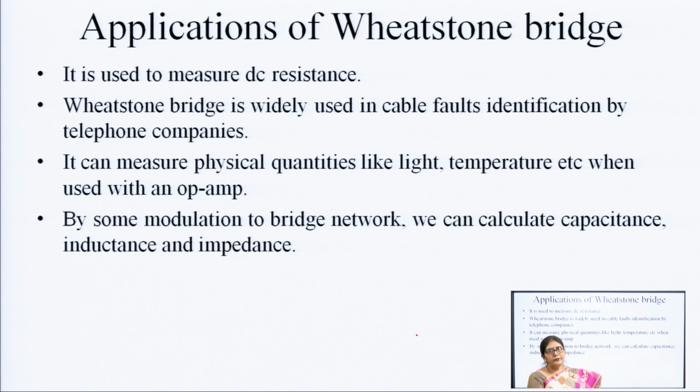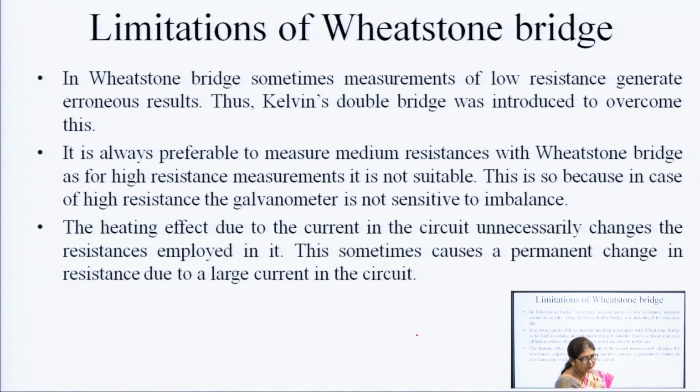So, the application of Wheatstone bridge: we can use it for cable fault finding, for the measurement of pressure, or for the measurement of temperature, and we are also using it in rectifier circuits. We can use it for the RMS measuring instrument, as we have discussed in the second lecture. In that also, in the true RMS meter, we have used the Wheatstone bridge. And after modification, we can replace the resistance by capacitance and inductance, and then we can measure the unknown value of capacitance and inductance also.